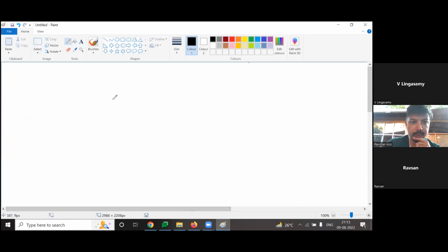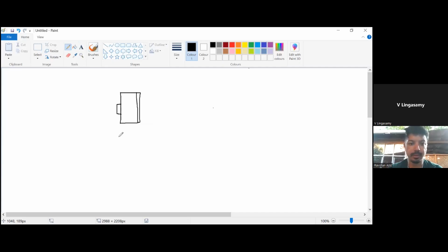Now, I need to quantify this. For example, you have a substrate and the ground plane. In CST, what we are going to do is excite a plane wave here. That is what you do in the Floquet port: you excite a plane wave. It can be single polarized or dual polarized, anything is fine. That is what you call Z max. You are going to excite this port.